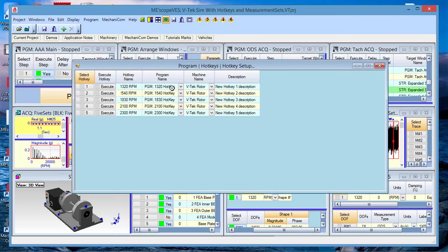So just imagine that maybe I'm doing impact testing. I'm using the system to do some impact testing, some qualification testing. I can do some curve fitting in MEscope, save those mode shapes into the database, and compare the values that I get, the frequencies, the damping, the mode shape, with some warning levels.